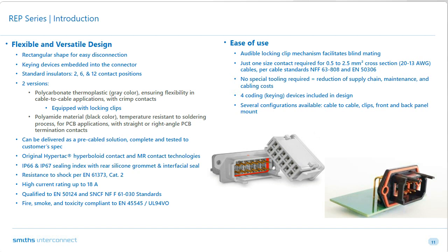And the one that you see on the bottom right is made out of polyamide material, black in color, as it shows in the picture. It is temperature resistant to soldering processes for PCB applications with straight or right angle PCB termination contacts. Now, this can be delivered, if this is what your application or your system requires, in a pre-cabled assembled condition, complete and fully tested to your specification.